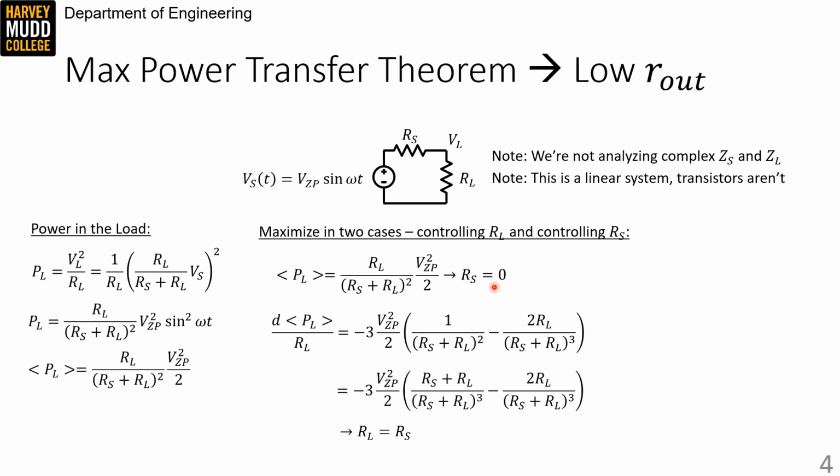Now, the fact we're dealing with large signals complicates that message a bit, since output resistances change with our bias point, but it's a good starting point to figuring out what an output stage might look like. For instance, we might say, let's start with an emitter follower. Those have low output resistances.